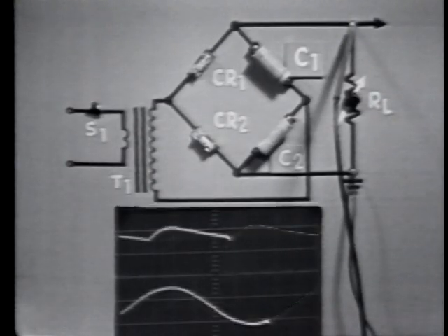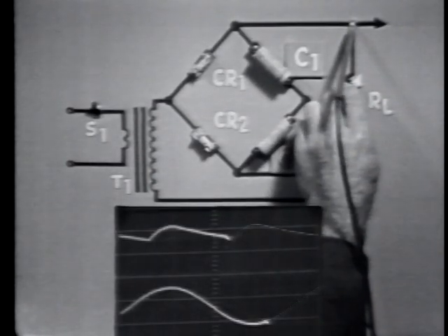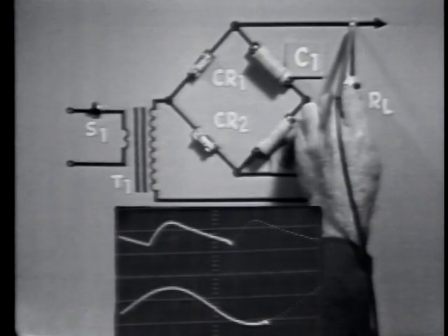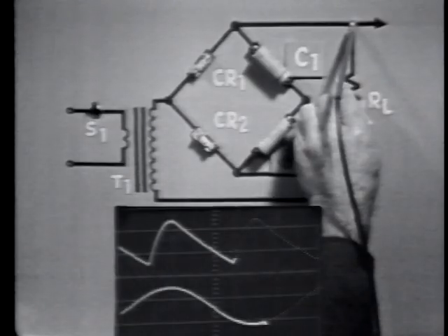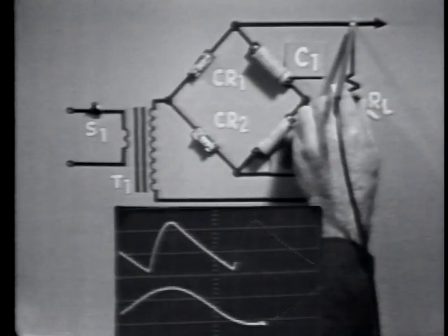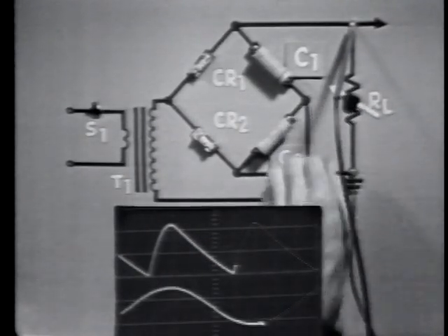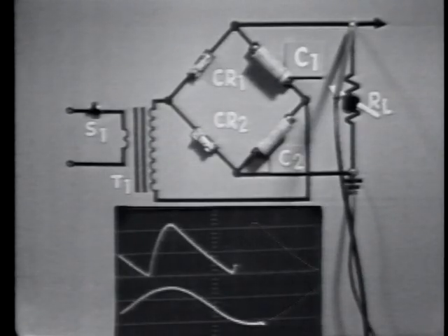Decreasing the value of resistance, or increasing the load, increases the current drain, and the average output voltage decreases. Notice also that the ripple amplitude has increased. These effects of a load change occur because the load change changes the discharge time of the capacitors.